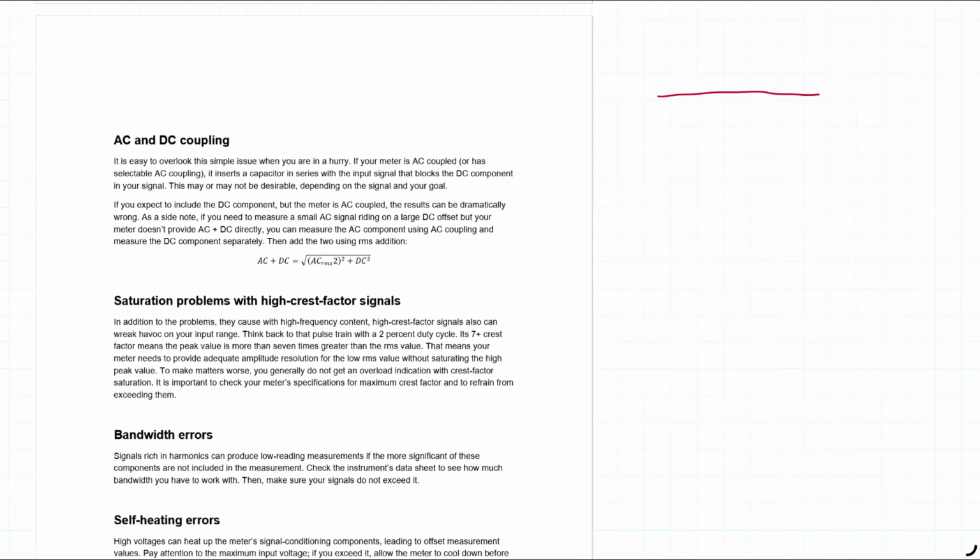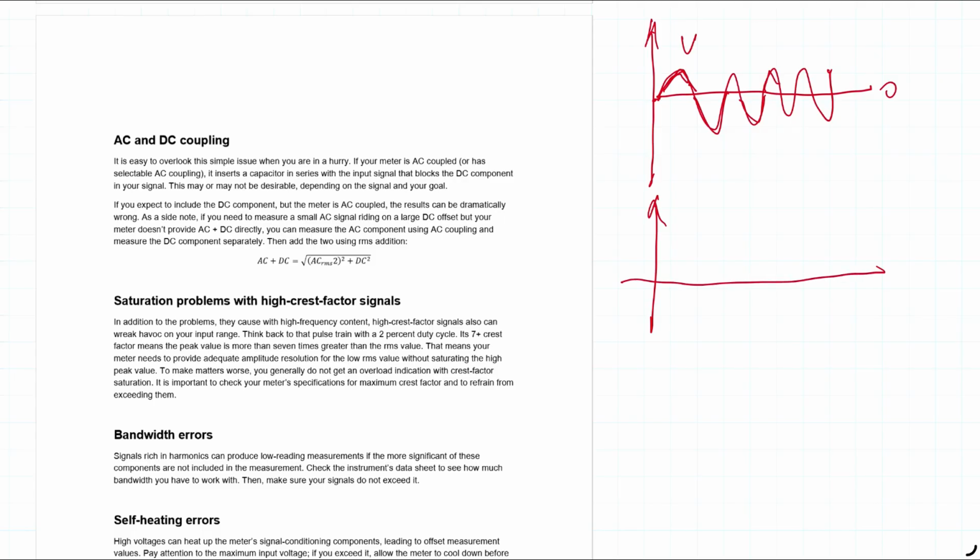normally you have a wave, say, we assume this wave is a random wave like this. It's an AC coupled wave. That means in terms of time scale, this voltage signal goes above to the positive side, also goes to the negative side, then positive side next time. The mean, the average over a certain time length, will be 0. But in reality, most signals will probably look something like this, very similar to that, but you have a DC offset.